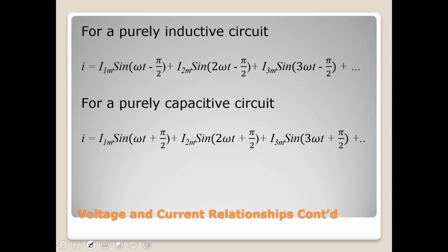So the angles are all in radians. In an exam, for your regular AC circuits, you know that we use degrees. However, once we switch to complex waves, although we are still doing basic AC circuit theory, put your calculator in radians. Please, please, please.